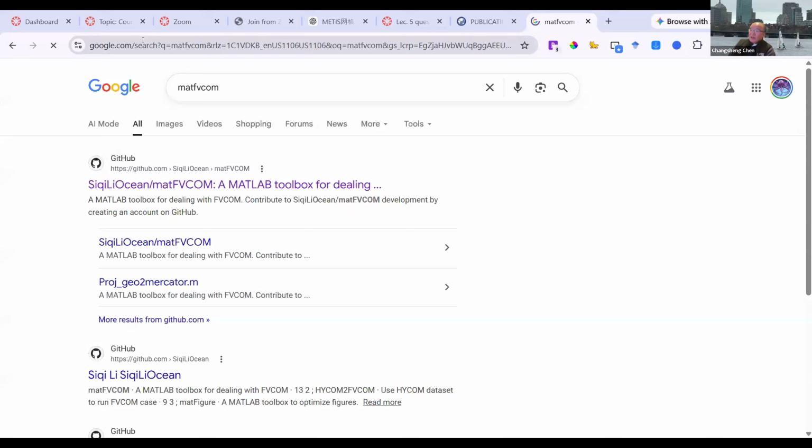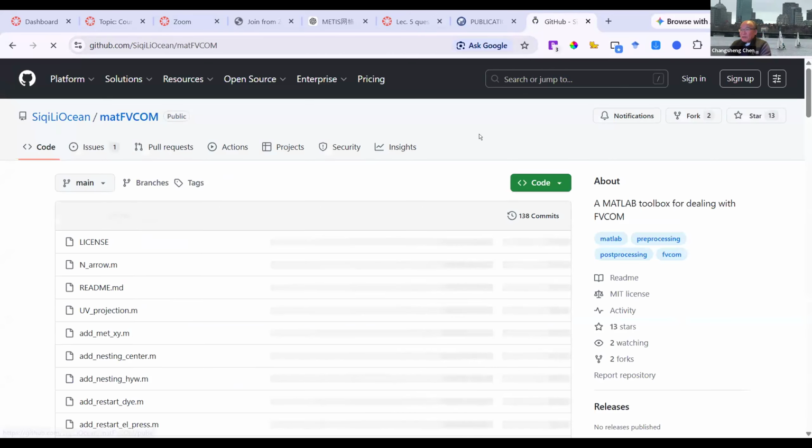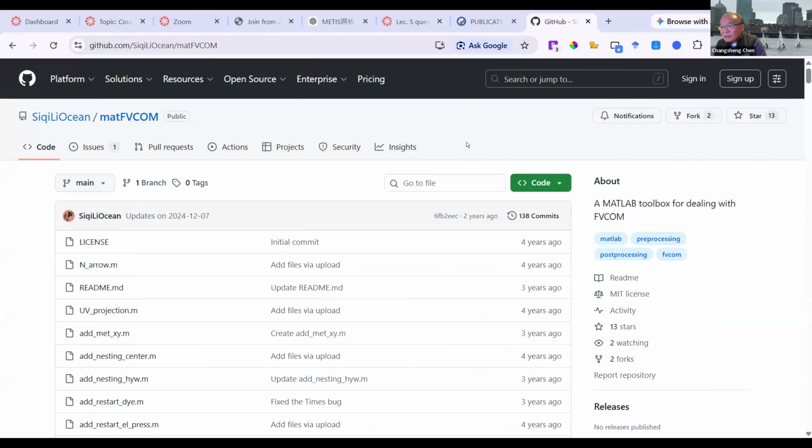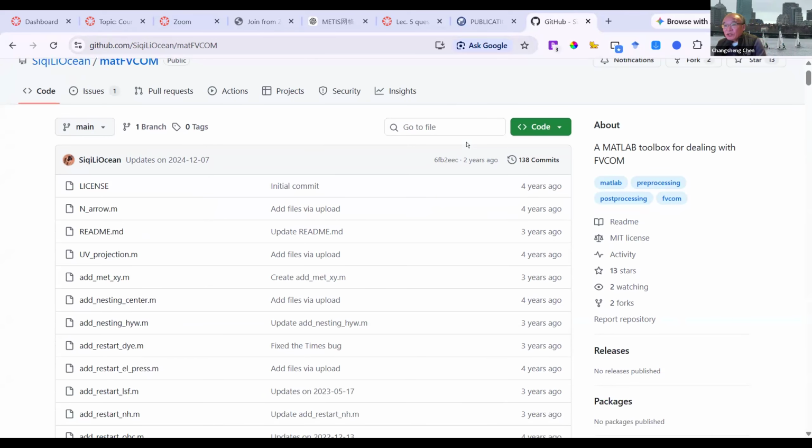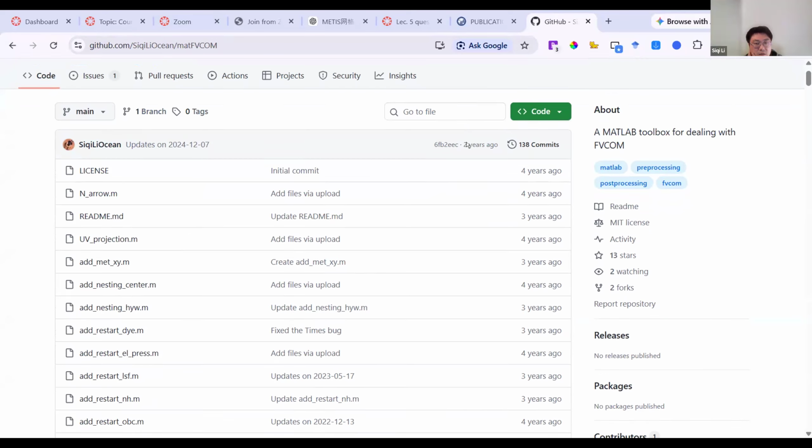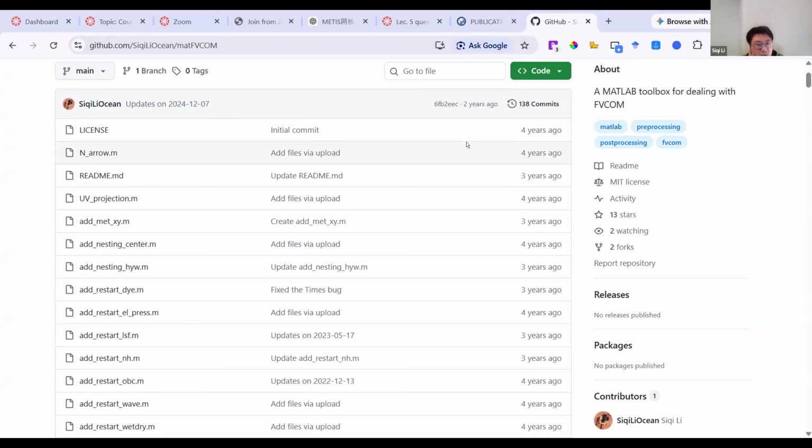Yunji, can you run the river case with FVCOM only, not the coupling? Yes, there is no error when I simulate only FVCOM. Then something in your coupling setup is probably not correct. I worry it is the radiation stress issue in the shallow region that Lu Wang met. He already fixed it, so I think you should get the updated code to see what happened. Okay, that could be one reason. I will ask Dr. Lu to send the code.